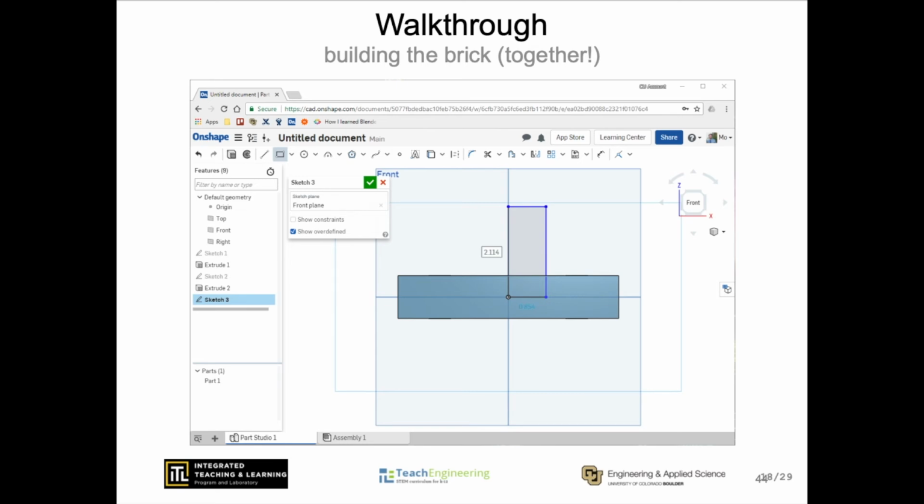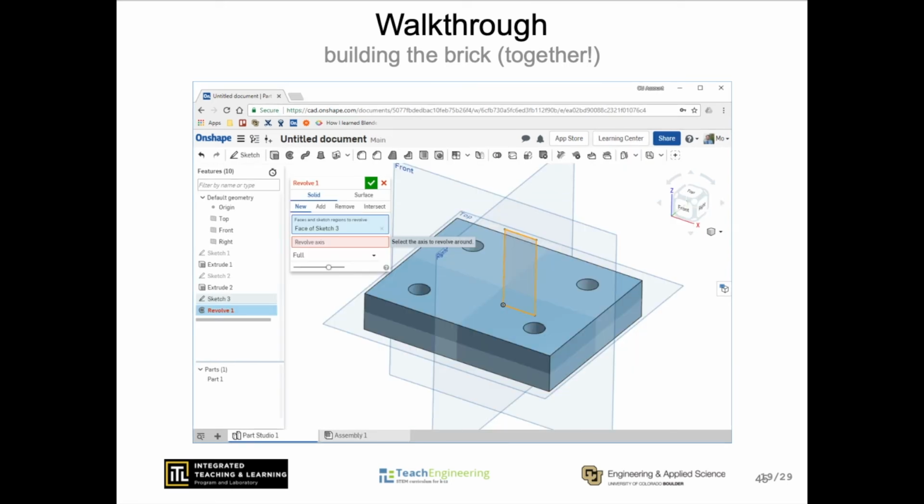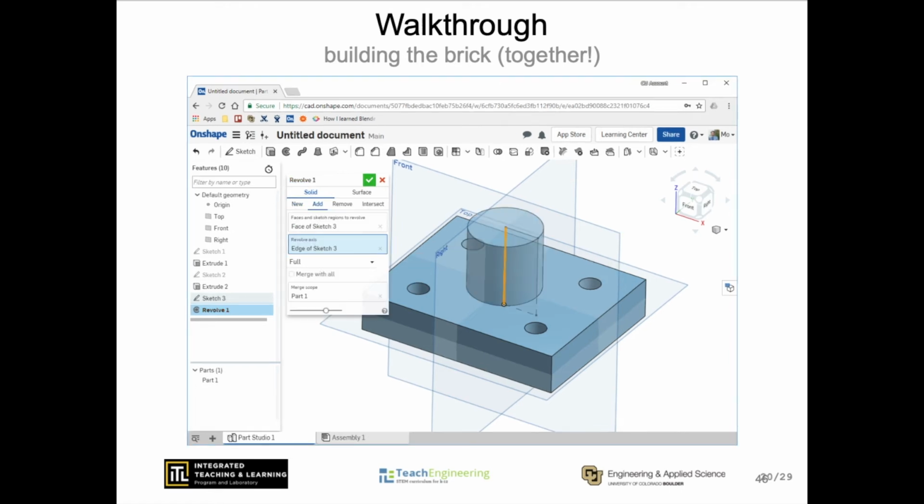Do we want to extrude this material? No. It will not double the material, it will simply merge the parts, so there is no point. Exit the 2D sketch mode to 3D mode. Select the sketch, and then you must manually select Revolve Axis to select the revolve axis. Choose the rectangle side that is vertical to the origin. This is what it should look like.